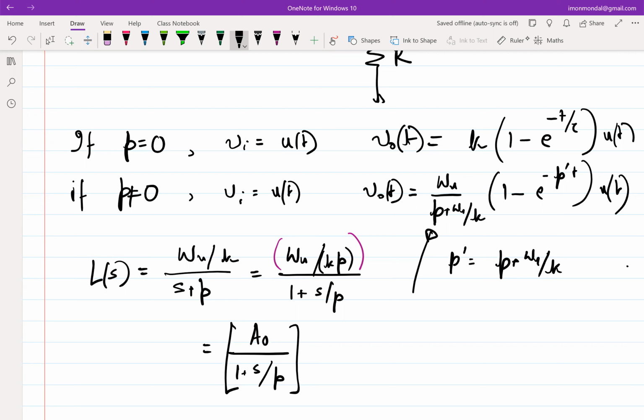And this additional term is essentially what? This is nothing but K times 1 by 1 plus 1 by the DC gain of the loop. Okay, so what is this? This also makes sense because ideally you would want the DC gain of the loop to be infinite. So when P equal to 0, in case of an ideal integrator, A naught is actually equal to infinity. So your steady state value is equal to K.